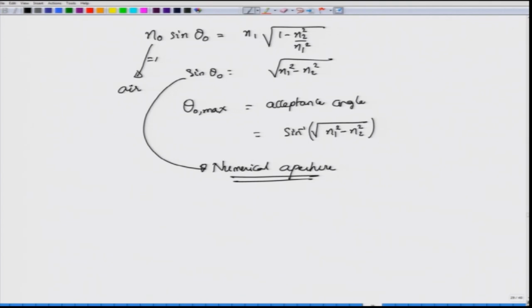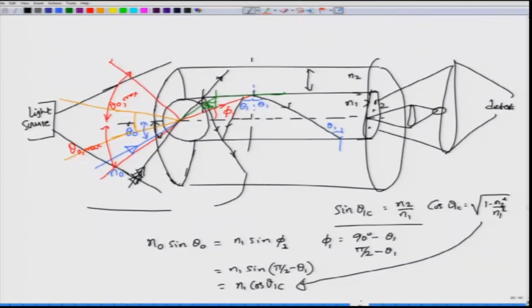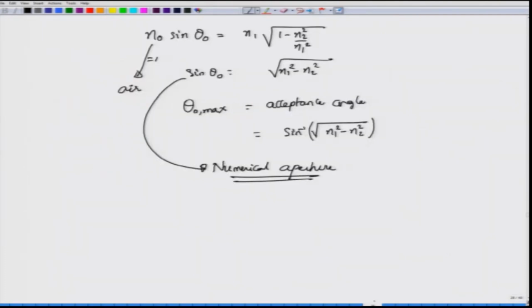So, this is a fairly standard analysis that I have done. I have in fact assumed a step index fiber, because I have not really looked at the graded index fiber and defined the numerical aperture accordingly for that one, but this should give you the basic idea of what this numerical aperture is all about. So, you want a fiber with a larger numerical aperture, but you then have to trade that off with the other things. We have also discussed the V parameter, right.